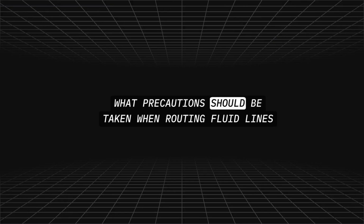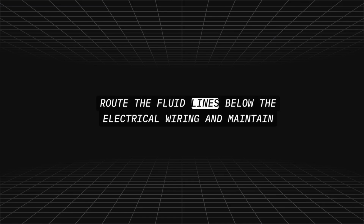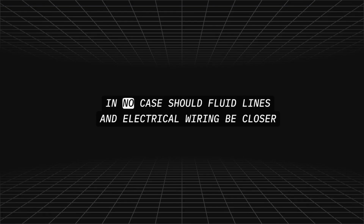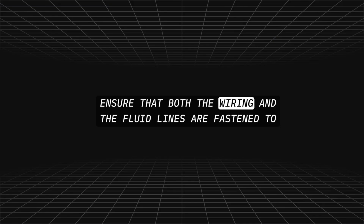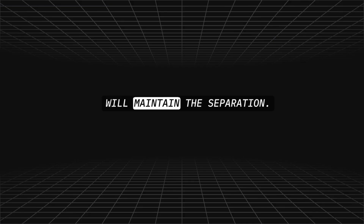What precautions should be taken when routing fluid lines adjacent to electrical wiring? Route the fluid lines below the electrical wiring and maintain a clearance of at least 6 inches whenever possible. In no case should fluid lines and electrical wiring be closer than half of an inch. Ensure that both the wiring and the fluid lines are fastened to the aircraft structure by clamps or other methods that will maintain the separation.